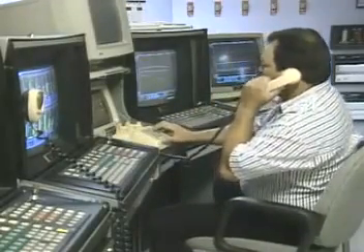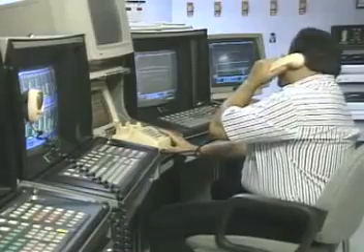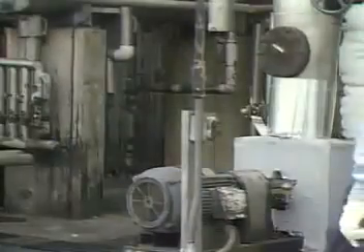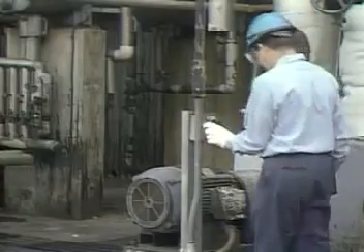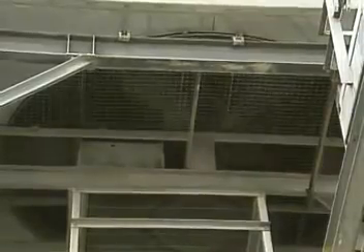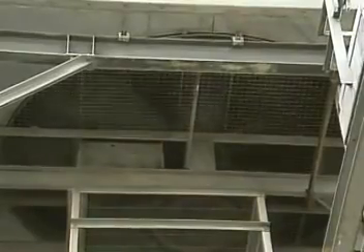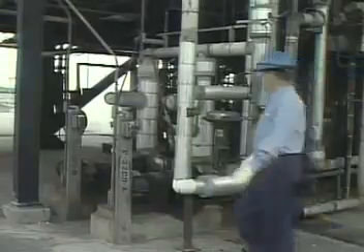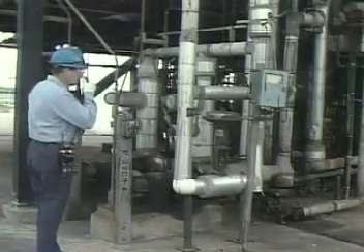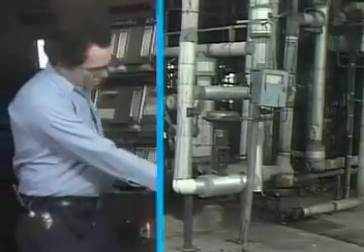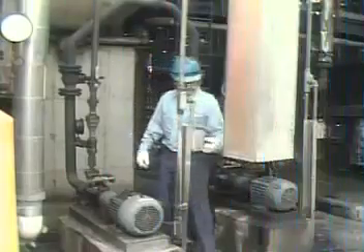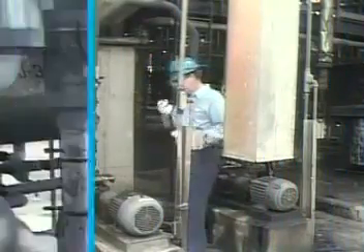But the basic goal of any emergency shutdown is to reestablish safe operating conditions. This often involves shutting down equipment that could pose hazards if it were allowed to continue running. Backup equipment may need to be left in operation to stabilize conditions. Once conditions have been stabilized, an emergency shutdown will likely involve stopping the flow of feed mixture to the column, stopping the takeoff of overhead product and bottoms product, and possibly shutting off the reflux system and the vacuum system.